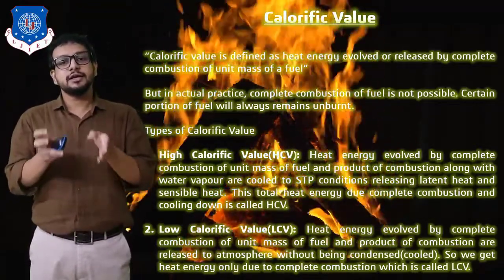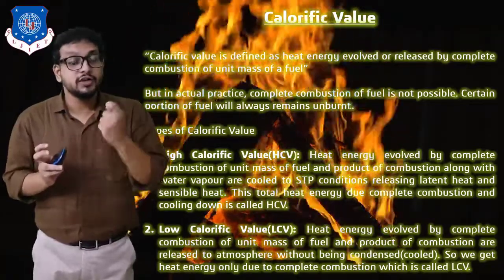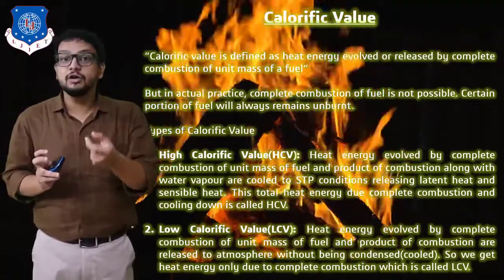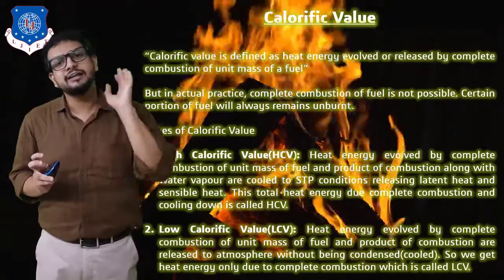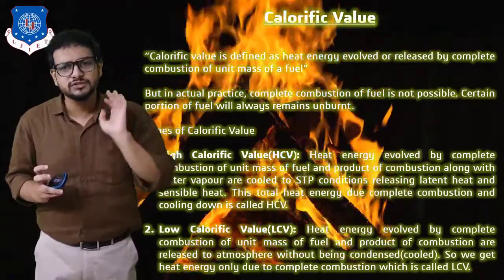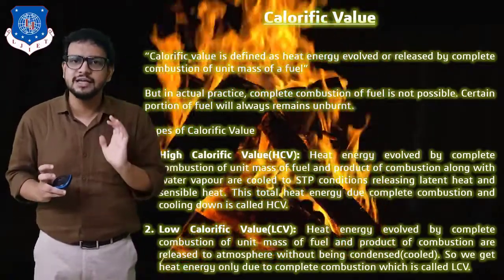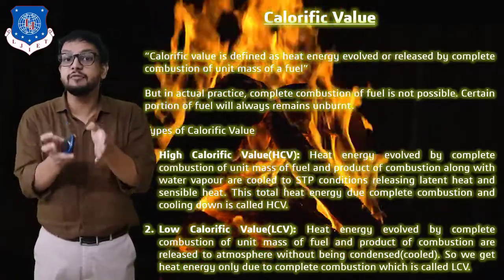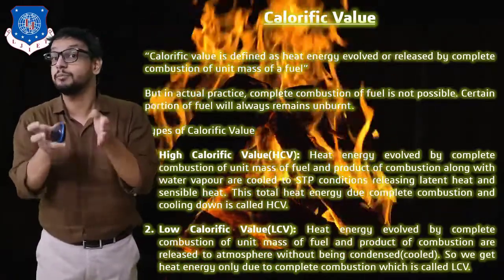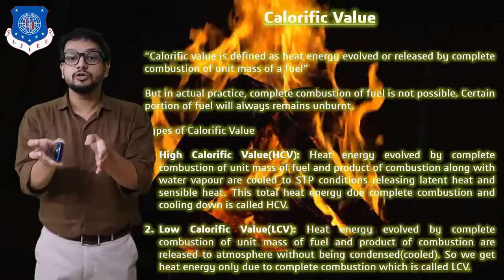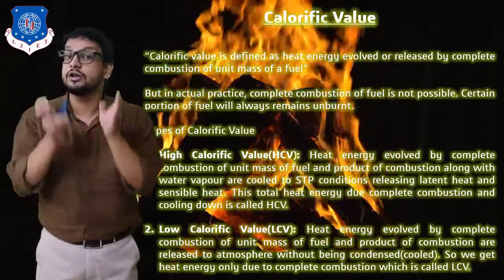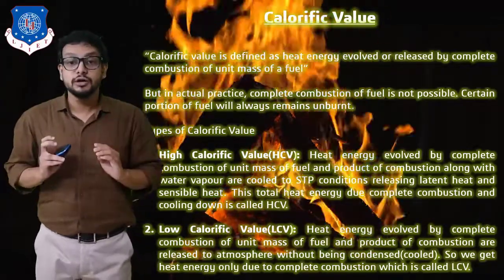Whereas in the case of low calorific value, if the water vapor released is not cooled down and is directly rejected to the surrounding atmosphere without condensing, then the heat energy generated is only due to the complete combustion of fuel. That heat energy is called the low calorific value of a fuel.